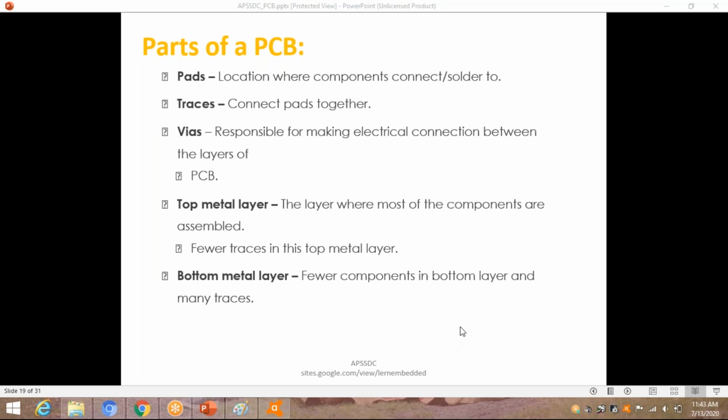Okay, Mr. K. Sai Charan, your doubt is about soldering in the middle layer. There is no need for soldering in the middle layers. Directly we will be giving tracks. Middle layers are only meant for tracks. There will not be any soldering in the middle layers.